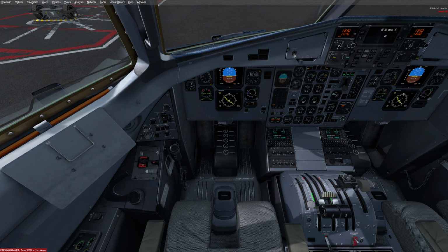And then on approach and landing, your flaps will be 170 at flaps 15, 160, gear down, flaps 25. Power management then to takeoff. It was in cruise up to that point. 150 knots, you want to go flaps 35. And by the way, your power levers on that final bit as you're reducing speed can go to flight idle at the lowest level, and then just adjust your power levers for your approach speed, and then just go ahead and land as you normally would. Autopilot Disconnect, you press it twice, and that should take care of business.